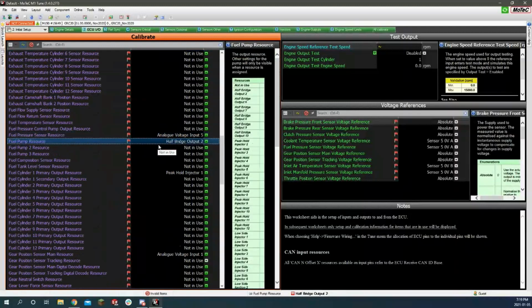I had another thought too with fuel pressure. We could run the pump straight off the ECU and PWM it if you want to do pressure, and then you can eliminate the manual pressure. So that's another thing that's possible. I did do a little bit of research on that. The problem with PWMing higher current sources like that is it creates a lot of heat. There's even a dedicated PDM, power distribution module, from Motec. I saw an example where it was even overheating, trying to power, I think it was a fuel pump.